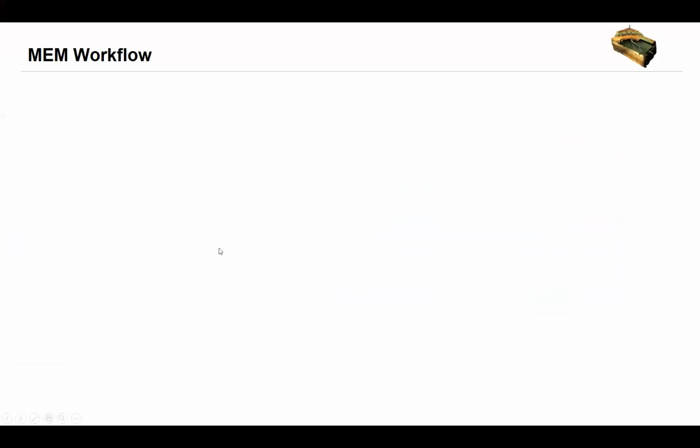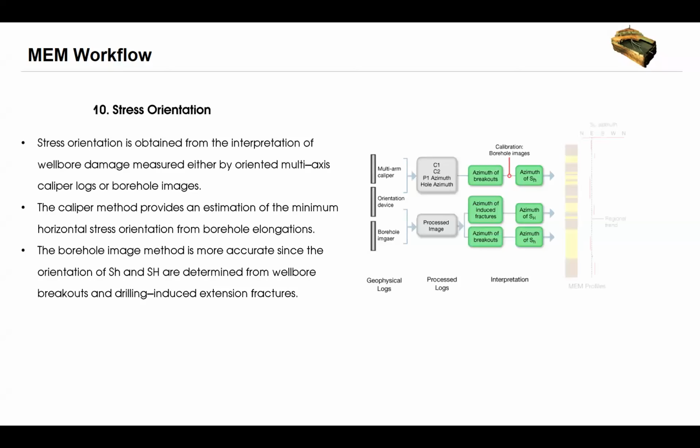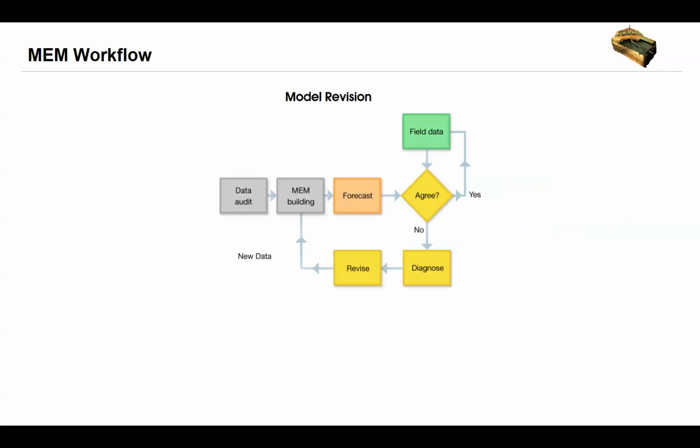I think that by making these steps, we are in our final steps. We have to mention that it is highly recommended that geomechanical models be revised as critical missing data or calibration data become available. Model revision can entail acquiring new data or simply improving calibration. The calibration of pore pressure, earth stress magnitude, and a better understanding of lateral variation in rocks' mechanical properties are typical examples of model refinement.